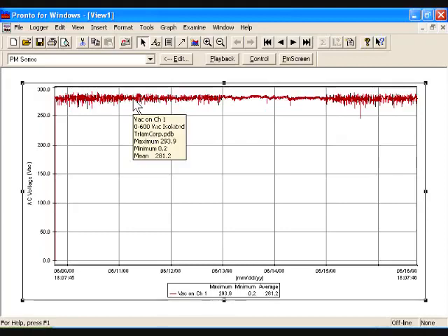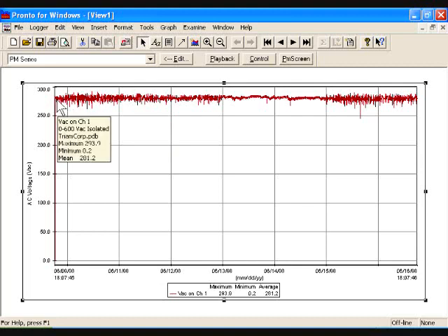Now, one thing I wanted you to notice is that the minimum here is 0.2, and I'm bringing this up to show a typical mistake that a technician will make: they will start the recording before they hook up the unit. And if you look down this end line here, you see a red on top of the black, and that's because the technician that did this recording started the recording and then clipped on a phase. We advise you to do that beforehand and then start the recording.